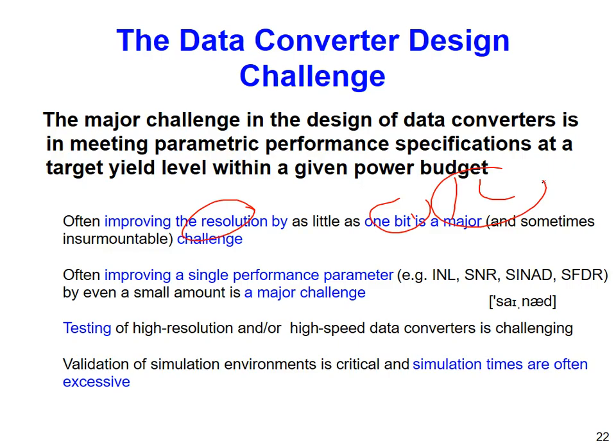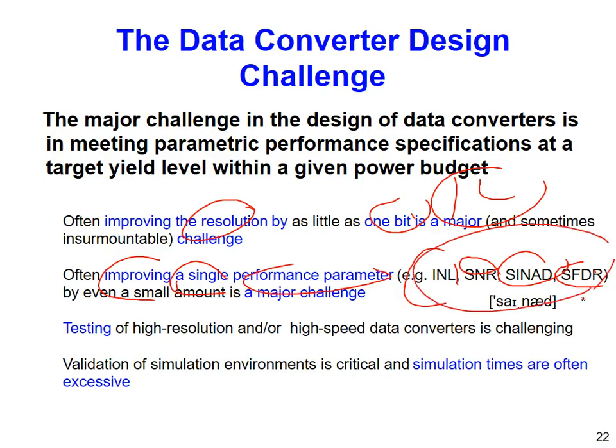And not only the effective number of bits, to improve even a single performance parameter, such as linearity, INL, SNR, signal to noise ratio, or SINAD, signal to noise and distortion, spurious-free dynamic range, any one of them is a major challenge.